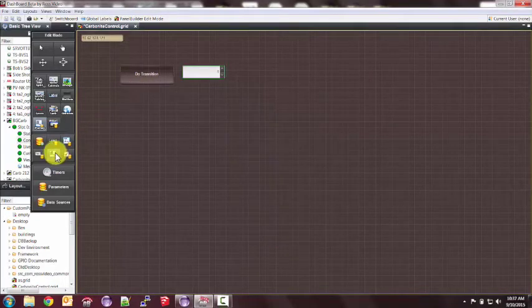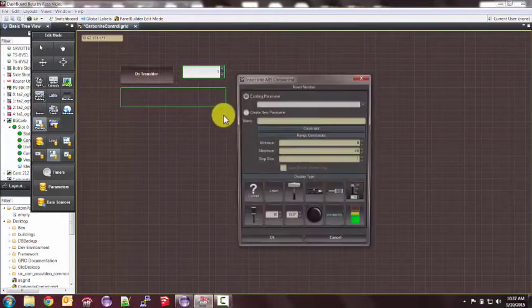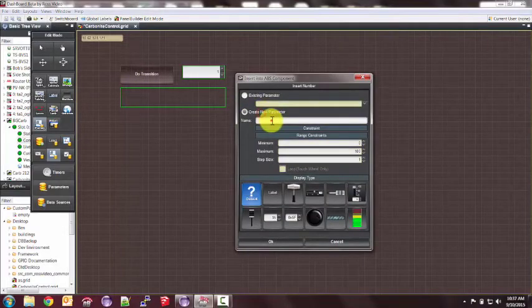And we're going to make it one of these spinners. Now the second one we need is how many frames this transition will take. So let's make that number a bigger element. We're going to create a new parameter. We're going to call it the transition rate. And it can go anywhere from 0 to, say, 500. And we'll make it one of these nice sliders.